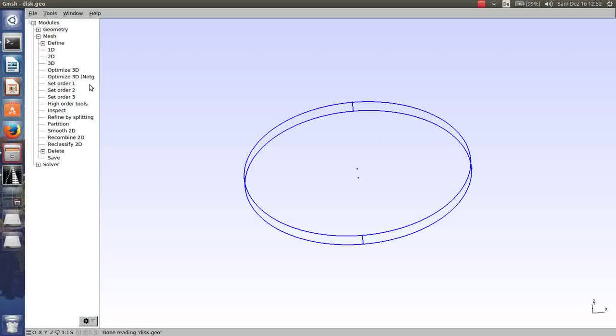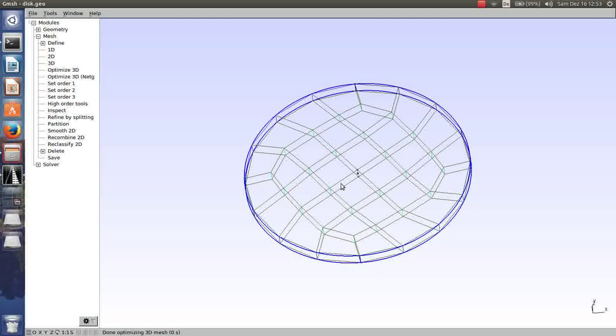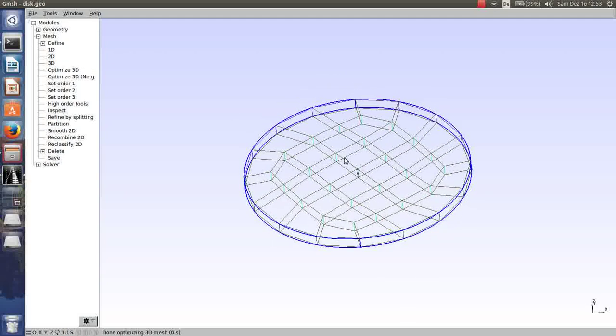This will work easily. sparselizard can handle a few 100,000 to 300,000 hexahedra in 3D for mechanics, or a couple of million quadrangles in 2D without any problem. But here the goal is to simulate the disk deflection using very few hexahedra but with a high interpolation order.